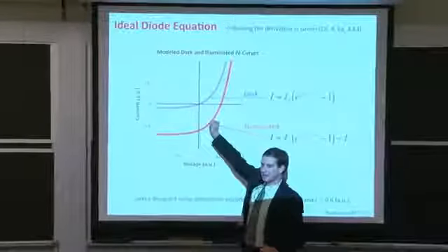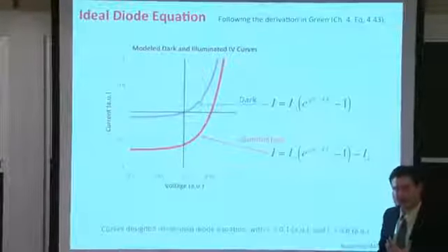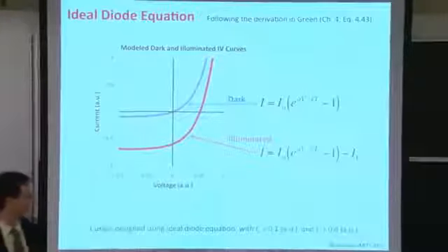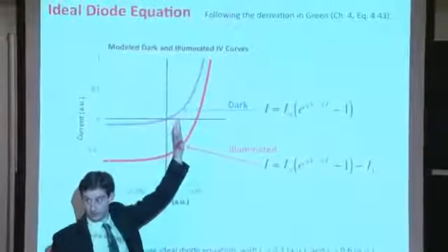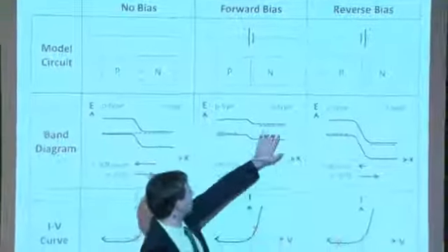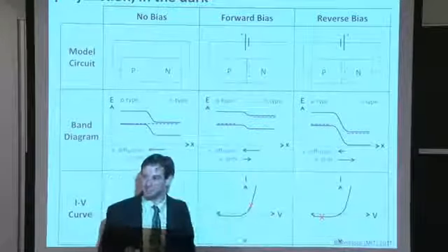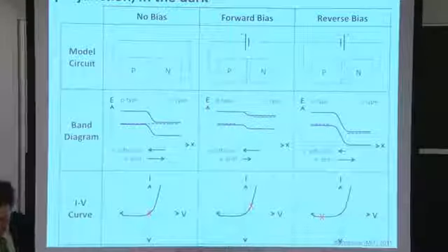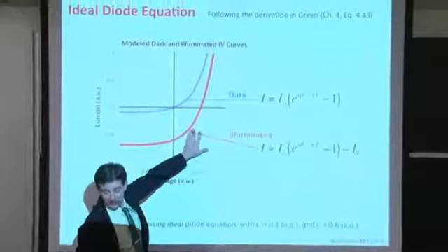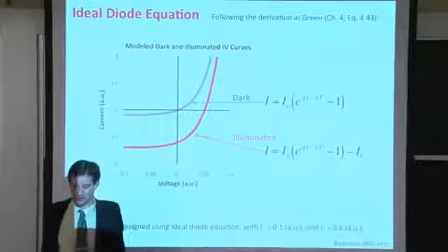So, we're beginning to develop an intuitive understanding of where electrons are flowing inside of our solar cells, in the dark and under illumination. The dark is important because we can test our devices in the dark, and we can still learn a lot about our solar cell device characteristics. As well, under forward bias conditions in the dark, we can force carriers from one side of the junction to the other the wrong way and probe for weaknesses in the p-n junction region, so that's helpful. In the illumination condition, obviously, we're testing the total amount of power that's coming out of our device. So again, this is very useful because it's off of this red curve here that we define the efficiency or the performance of the solar cell.